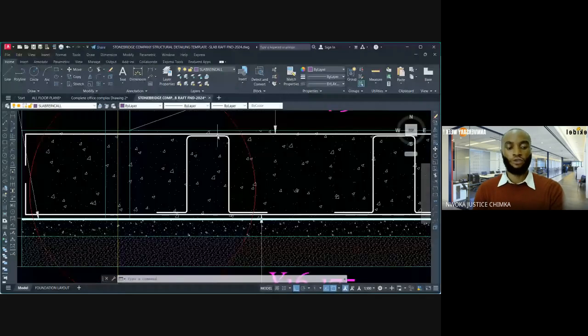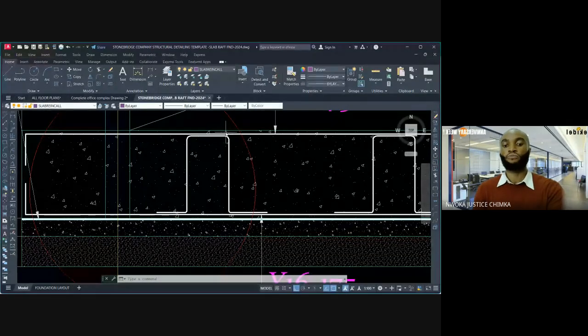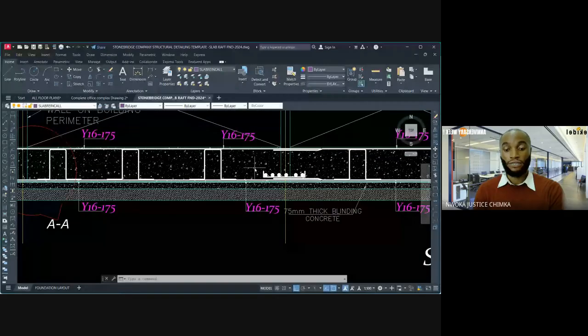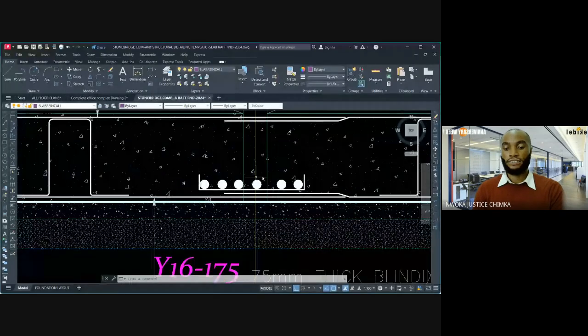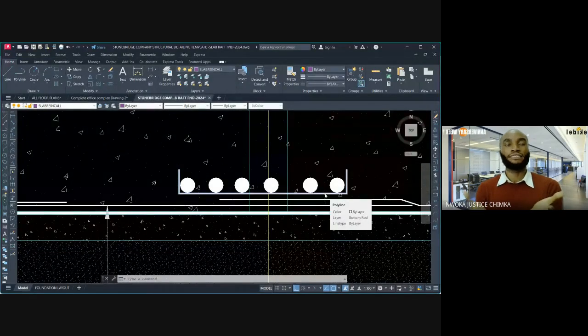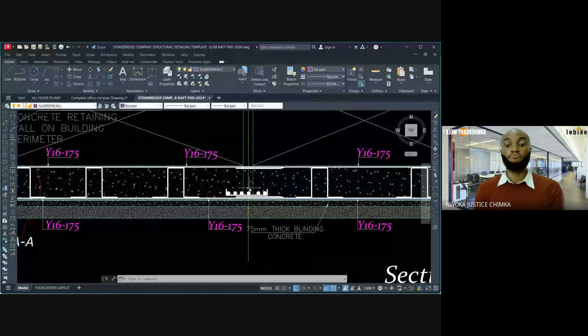Then, for example, we all know what this is. This is a shear bar, which is used to support this other top bar, to separate them and support them, else it will fall down from the top zone. So you can see now this is the additional reinforcement. It's basically placed like a pad footing under each of the major columns on top of the bottom bars.